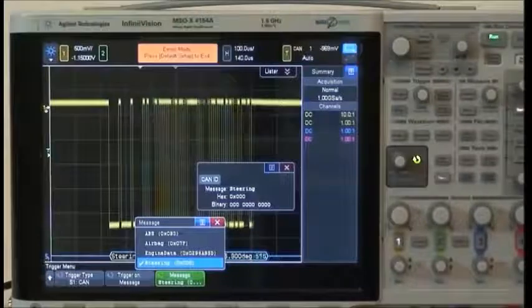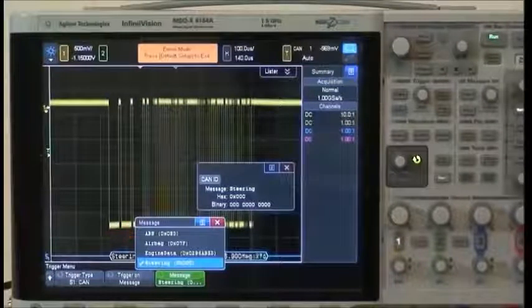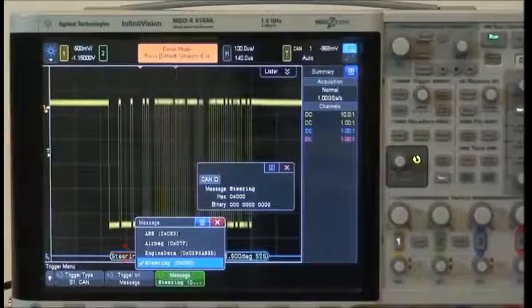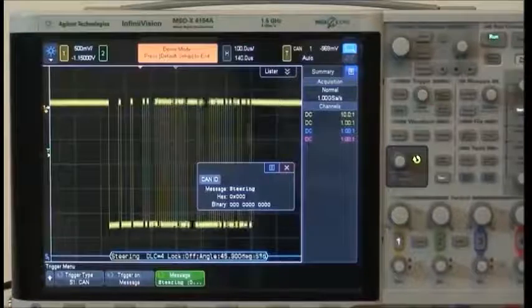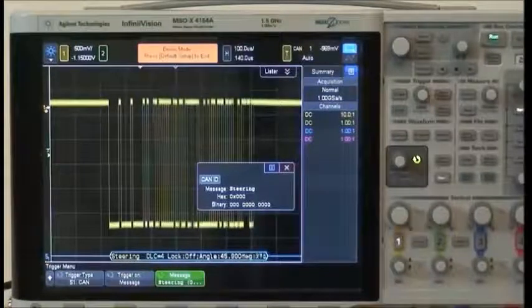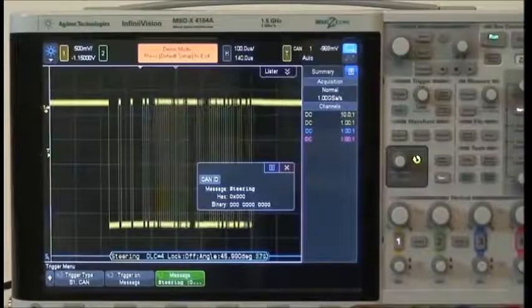For our CAN demo signal here, we only have 4 defined messages: ABS, airbag, engine data, and steering. Here we show the scope triggering on steering. For a high-speed CAN bus in a real vehicle, there would typically be many more possible messages to select from. Let's now see the various display formats of symbolic decoding besides just the time-correlated decode trace below the waveform.